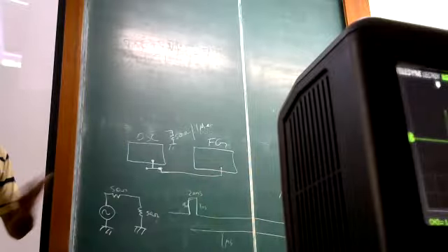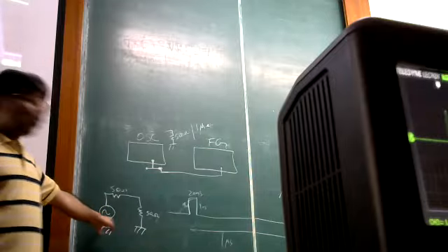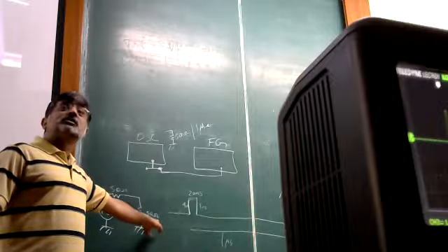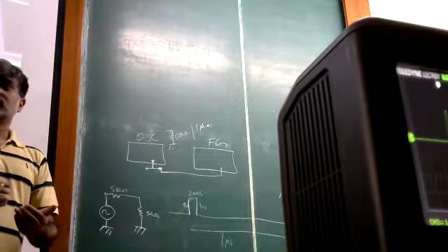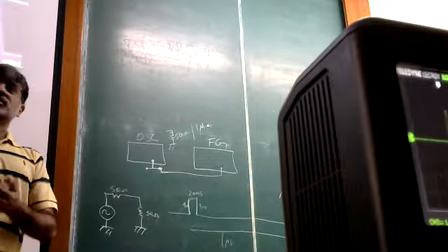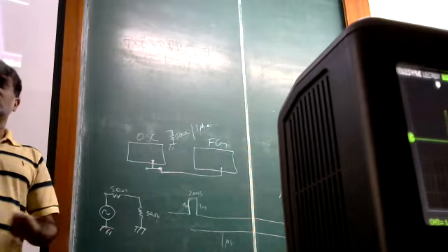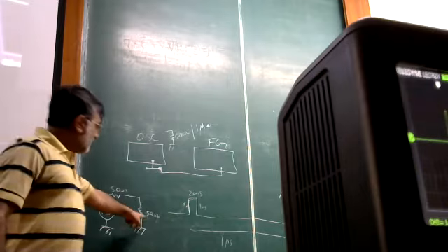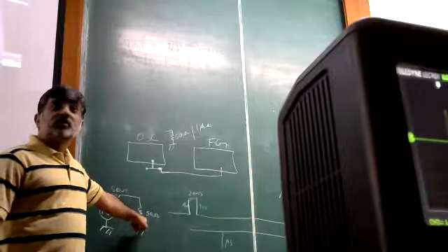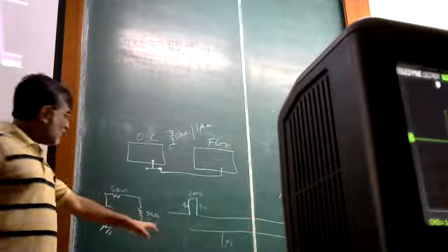So in order to make it convenient, the instrument actually displays the voltage that would be dropped across the 50 ohm load. This is actually the reason I'm telling you that this is a convention. When you take a microwave source and it says power output 0 dBm, or 1 milliwatt or something, that power is referring to the power which is actually going to be dissipated across a 50 ohm load which you have kept here. Why am I making a big point of it?